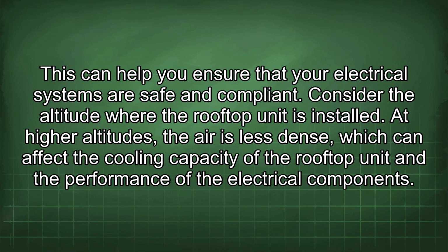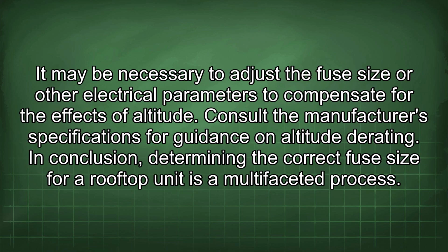Consider the altitude where the rooftop unit is installed. At higher altitudes, the air is less dense, which can affect the cooling capacity of the rooftop unit and the performance of the electrical components. It may be necessary to adjust the fuse size or other electrical parameters to compensate for the effects of altitude. Consult the manufacturer's specifications for guidance on altitude derating.